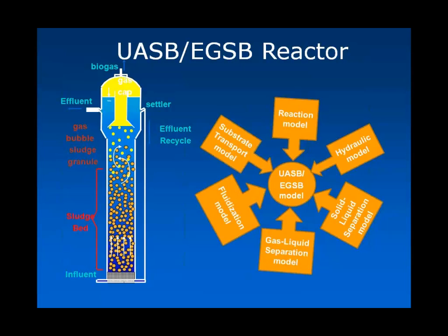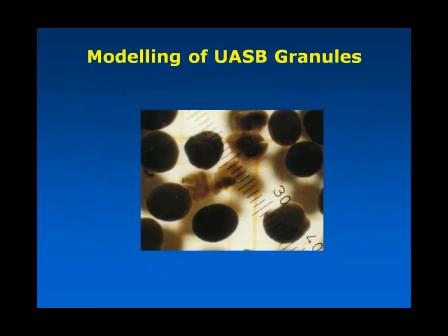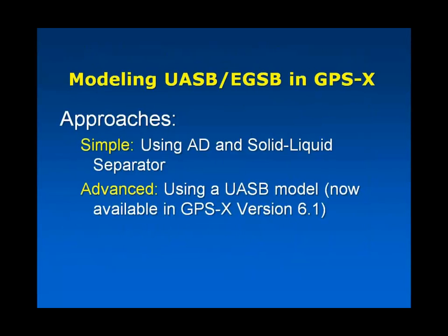There was the possibility to go down the route of the one-dimensional diffusion models like our biofilm models. There was a lot of complications with that because the granules themselves kind of grow and change, and the surface area on them changes as well. So what we decided to do was to create a model that allows us to do the biological treatment part in the way that we would do normal anaerobic digestion in a completely mixed manner, but then we also impose a granule bed on it as well.